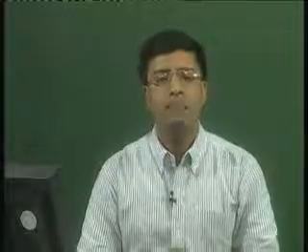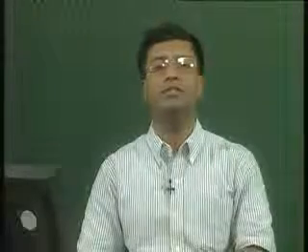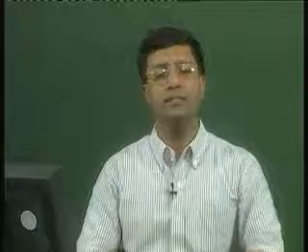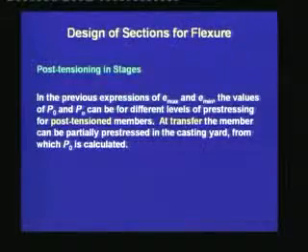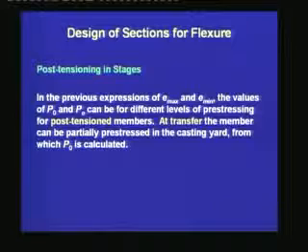We are learning one concept which is helpful in avoiding stresses going beyond the allowable values, and this concept is called post-tensioning in stages. In the previous expressions of Emax and Emin, the values of P0 and PE can be for different levels of pre-stressing for post-tension members.